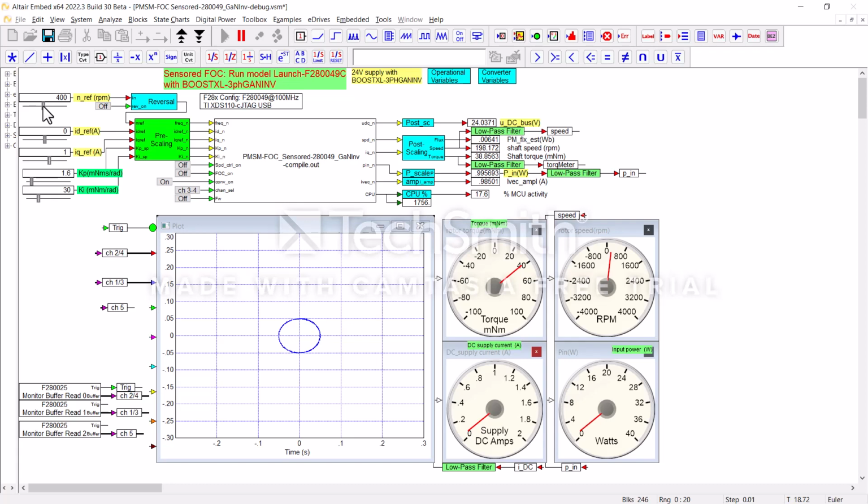So if there's any load on the motor, here I'm changing the motor speed. Or if I try and motor it too fast without moving up the IQ, it'll stall. So I can just turn on the FOC. Now we're running with the encoder. I can turn on the speed control, and I can move the speed up. I don't know if you can hear it, the motor spinning right here. Got some tape on my fingers. I'm moving it nice and slow. There we go.